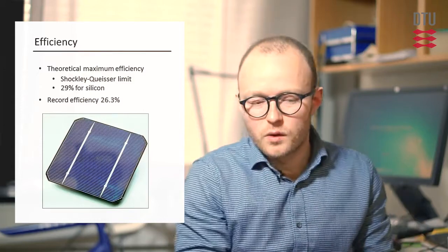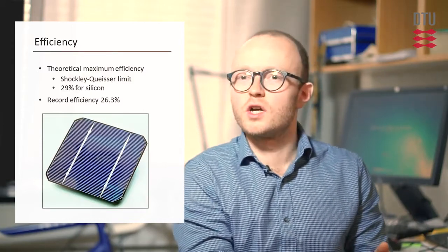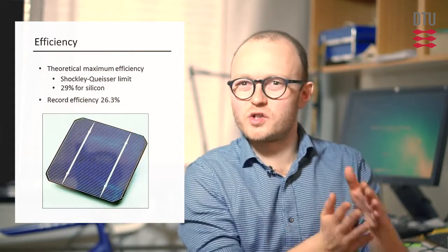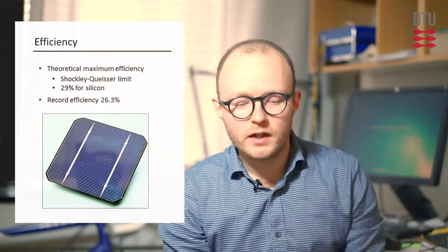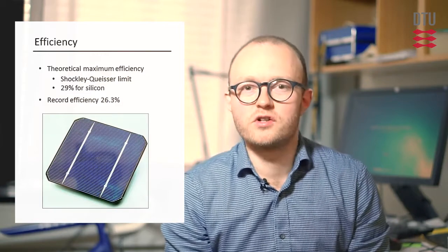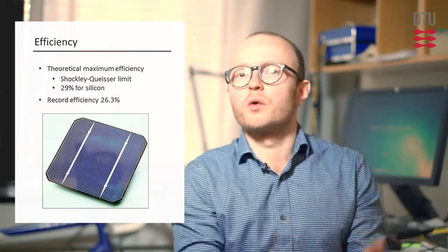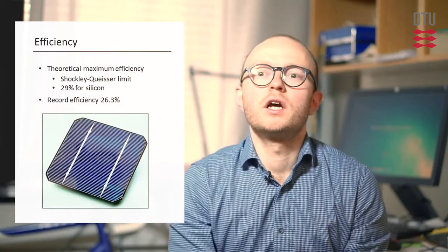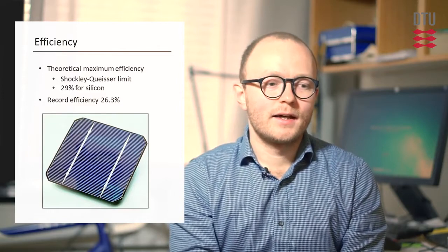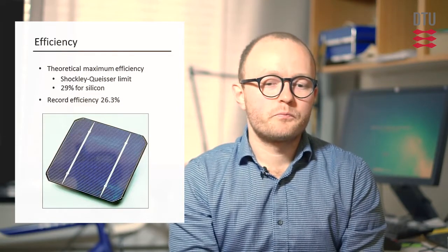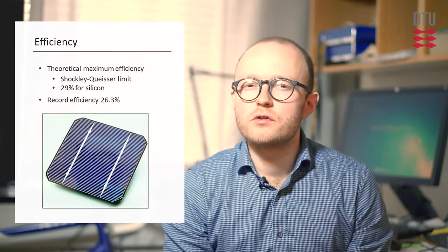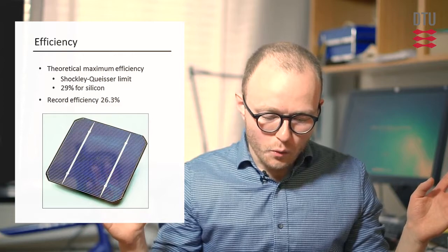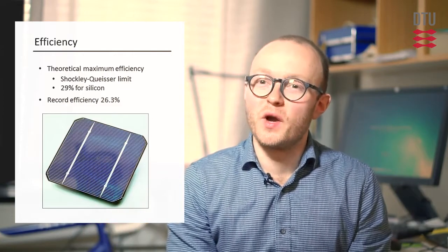What's not so ideal, or what's challenging, is how do we produce volumes equivalent to the silicon solar industry today with those thin wafers. So there are a couple of companies and also research activities going into how do we do that. Should we grow a wafer epitaxially from silicon? Should we make wafer production a bit like the multicrystalline production, where we cast the wafers in a mold?